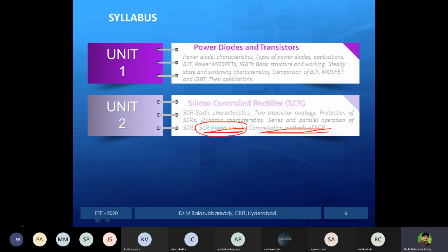Control means that when it has to be on, we are able to decide that at a particular instant we want to fire, use that circuit, and fire with alpha of 30 degrees or 60 or whatever. That is turn on. Here in the case of SCR, one thing is a very important note. Once it is on, let it be. There is a switch, and the supply is here. For this AC supply, I am connecting one thyristor here.